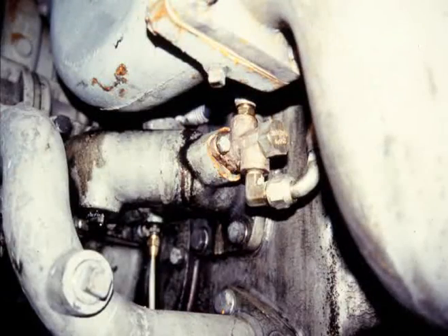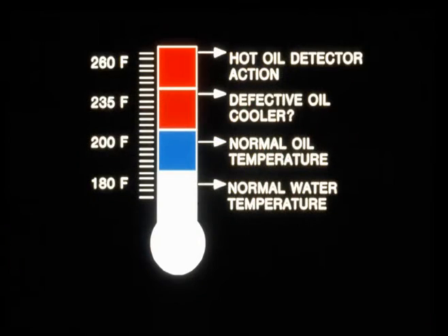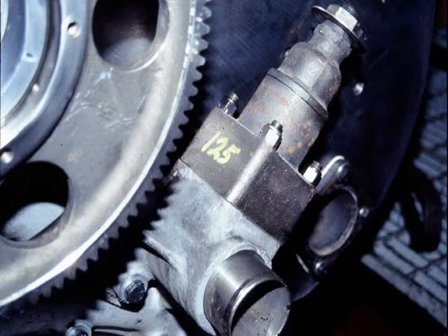First, a thermostat is used to detect oil that is too hot to safely provide lubrication. Should temperature exceed 270 degrees Fahrenheit, a low oil shutdown will occur. Secondly, a lube oil pressure relief valve prevents pressure above 125 psi from entering the engine.